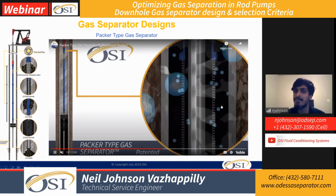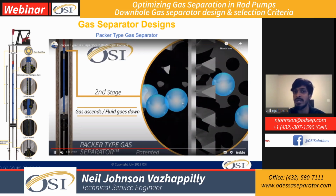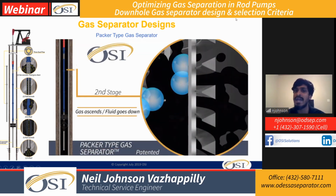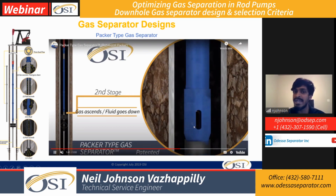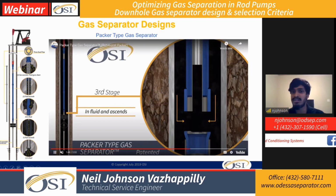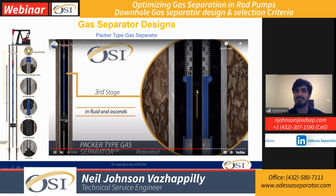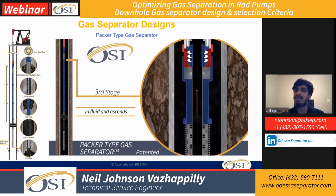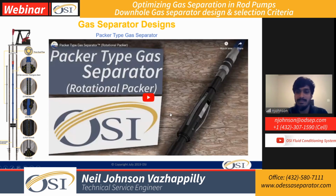The majority of the separation happens in this section right here, where the gas bubbles are coalescing because of the screen as well, and then traveling upwards through the annulus, with the fluid being denser, falling down due to gravity, and going to the intake section. This intake section, like I mentioned, is the design because of which we can allow this system to work the way it's supposed to. And finally, through the dip tube, whatever free gas we still have, we compress it back into solution and pump it. So that is what we have for the packer type separator.